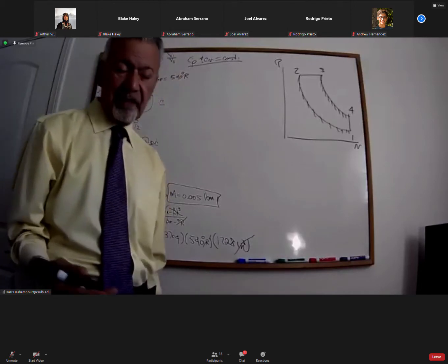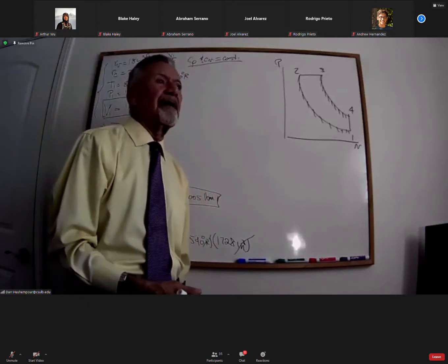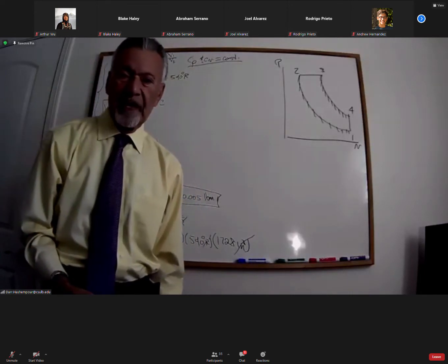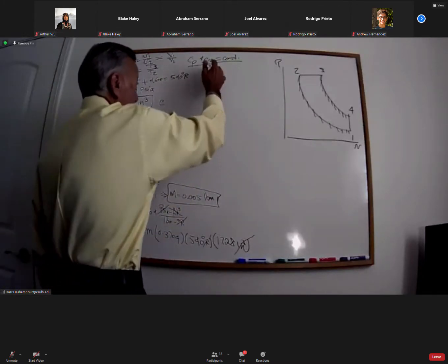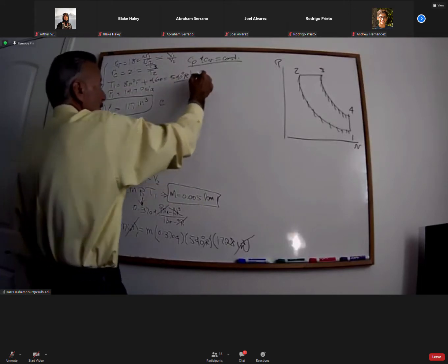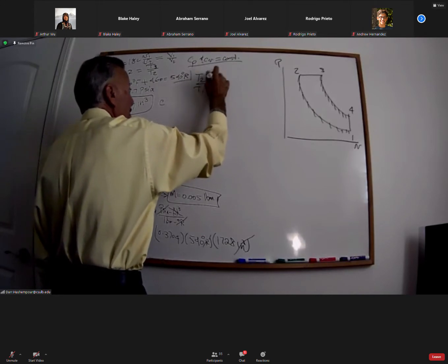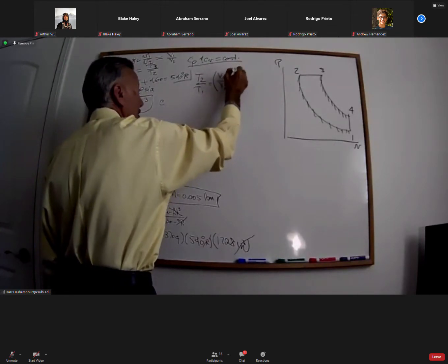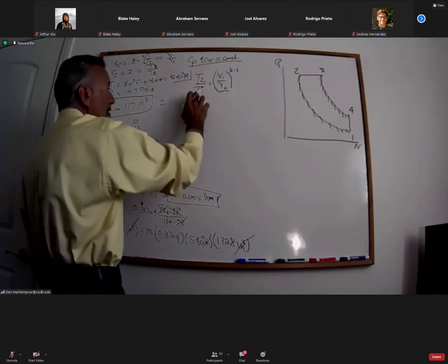That's one of the tricks. Sometimes it's utilizing room temperature, or the temperature remains at 300 degrees Kelvin. All of that means Cp and Cv are constant. Since that's the case, I have a T1, so I need to find a T2. T2 over T1 is equal to V1 over V2 to the power of K minus 1. This is given 18. T1 is given 540.